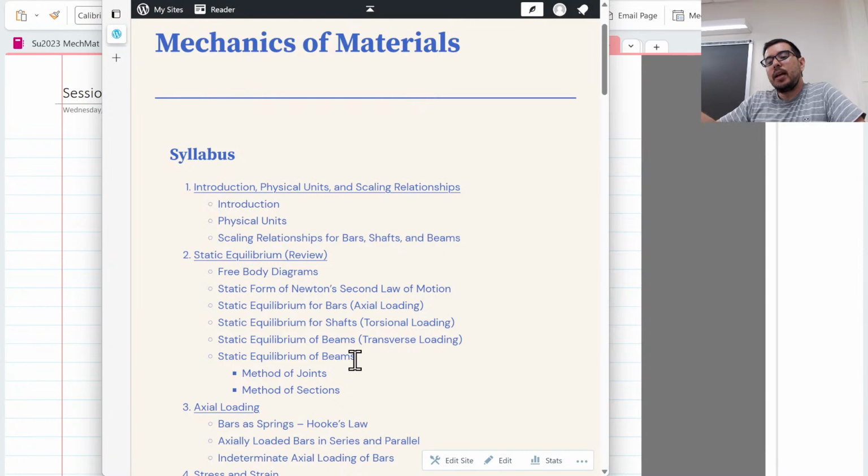And from that, once we know what the stresses are in the structure, we can then make some estimates for whether or not that structure will fail. Okay. And how do we know that? Because we have this big structure with distributions of stresses, but we go back to the simple testing that we did on a material, or someone else did on a material that they put on a spec sheet. And with that, we can tell whether or not the stresses we have are going to exceed the stresses that they found when they tested the material by itself.